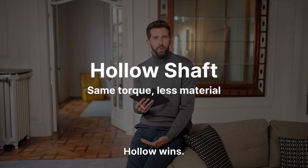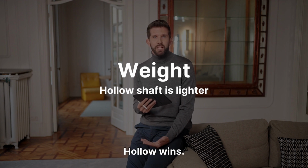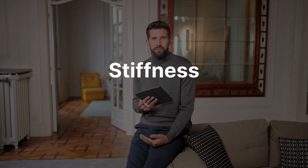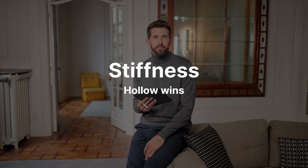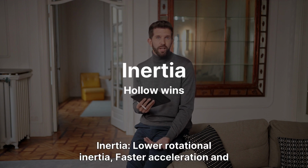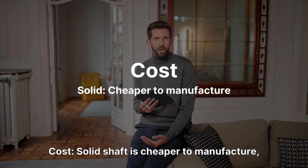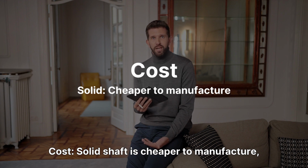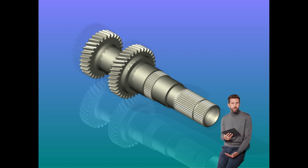Hollow wins. 2. Weight: hollow shaft is lighter, reduces load on bearings and supports. Hollow wins. 3. Stiffness: for same weight, hollow shaft has better torsional rigidity. Hollow wins. 4. Inertia: lower rotational inertia, faster acceleration and deceleration. Hollow wins. 5. Cost: solid shaft is cheaper to manufacture, hollow needs precise machining. Solid wins.